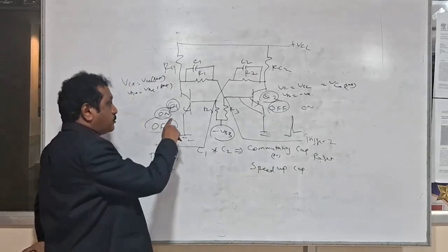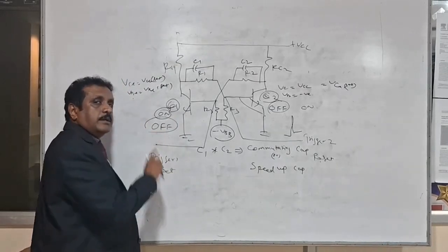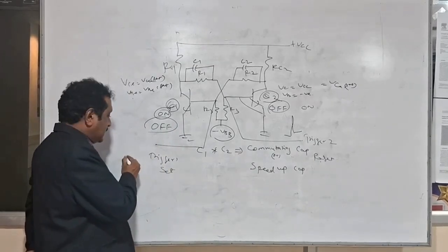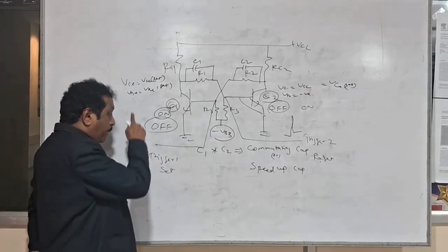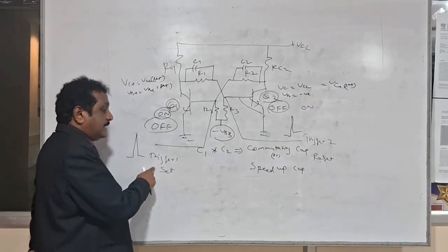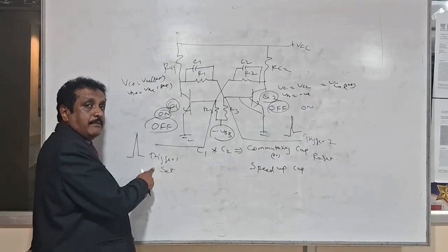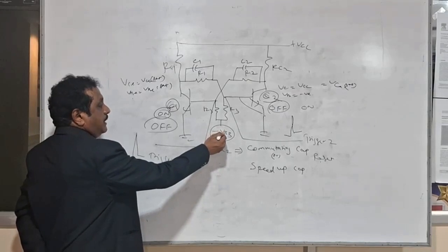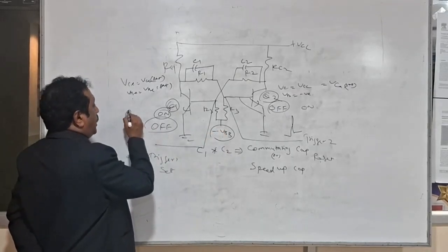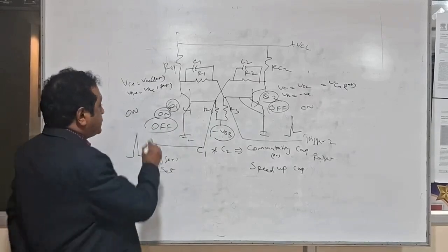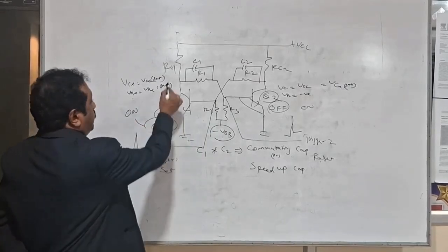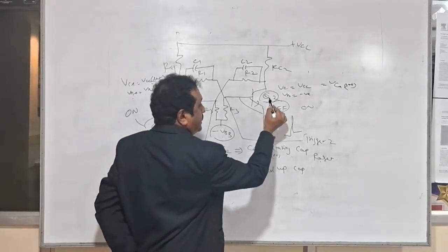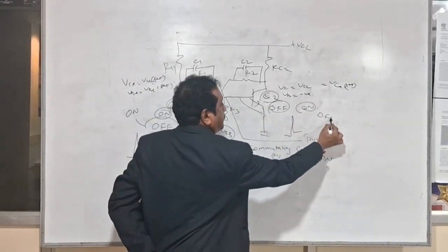Now we are going to switch Q1 from off to on. In order to make the transition, we apply an external positive-going trigger pulse at the set point, trigger 1. When it overcomes minus VBB, that makes Q1 on again. Once it goes on, its collector voltage is VC saturation, 0.2 volt. That makes Q2 off.